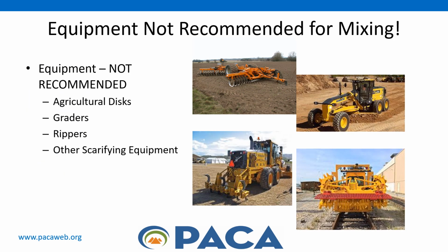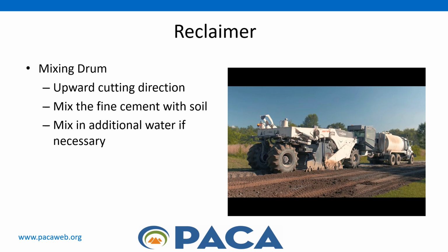For your information, the following equipment is not recommended for pulverization of the subgrade: agricultural discs, graders, rippers, and other scarifying equipment. The reason is they cannot achieve the proper degree of pulverization needed. A reclaimer is the correct equipment for the job.